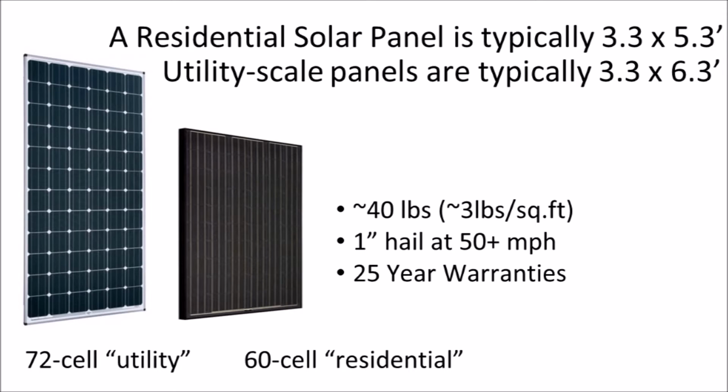And the difference between a residential 60 cell panel compared to the utility scale 72 cell panel is these extra 2 rows of cells, which give the module a little bit more height, weight, and voltage. A larger panel, such as the 72 cell panel, means slightly more bang for your buck all the way through the project. But the problem with 72 cell panels is that they're a little too tall and a little too heavy for one person to safely handle on a slanted roof.